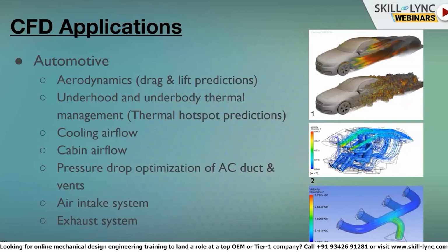Then you have hot parts placed in the underhood and underbody, like the exhaust system, manifold, and engine, and all the neighboring components have a risk of catching fire at certain vehicle operating conditions. So you need to simulate it. You need to find the maximum temperature each component experiences in the vehicle. If it goes beyond its design temperature, you need to work on how to protect it.